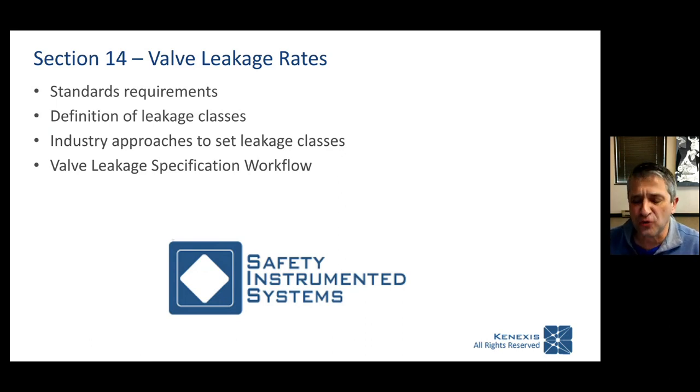And if you do truly need a positive shutoff, using a single valve to achieve that shutoff is a wildly bad practice. So if you absolutely need isolation between one atmosphere and another, relying on a single valve to provide that for you is crazy.